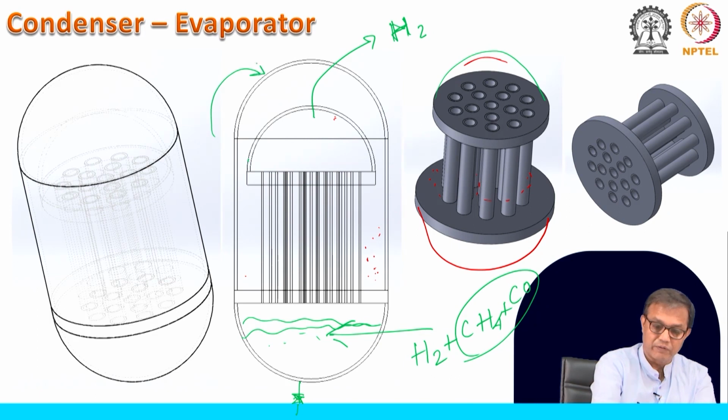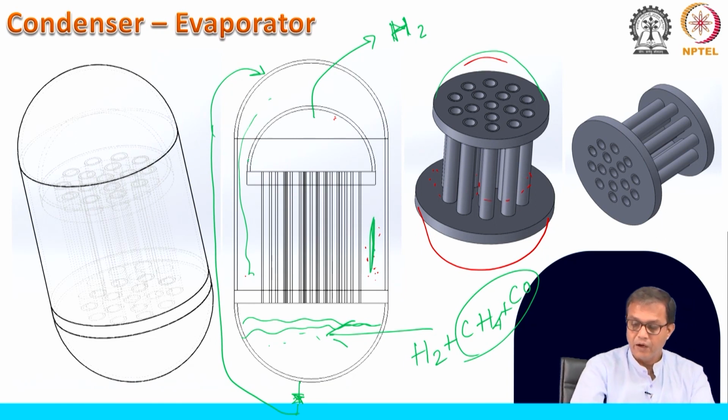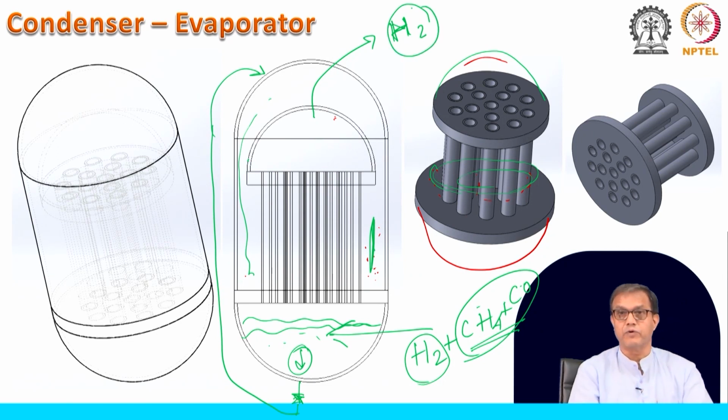in the air liquid process. So, this was high pressure gas, we have expanded it and put it on this side. So, this will be collected over here. Outside this tube we have this liquid methane plus CO, and inside we have the vapor where this CH4 plus CO will condense and be collected over here. The hydrogen in gaseous form will be collected from the top.